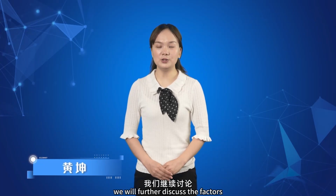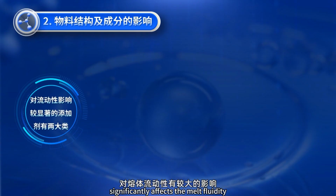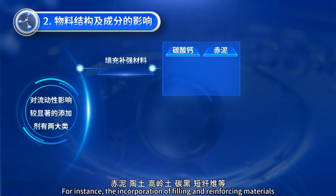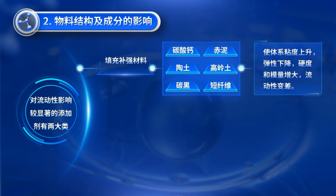Hello, everyone. Continuing from the previous lesson, we will further discuss the factors influencing the shear viscosity of polymer melts. The addition of additives to polymer melts significantly affects the melt fluidity. For instance, the incorporation of filling and reinforcing materials such as calcium carbonate, red mud, pottery clay, kaolin, carbon black, and short fibers increases the system's viscosity, reduces elasticity, increases hardness and modulus, and worsens fluidity.